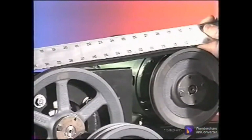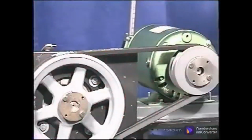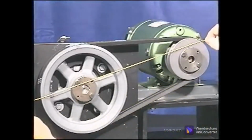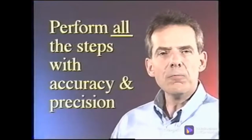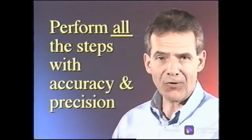When installing new belts, set the tension 1/3 tighter and check it after the first few hours of running, adjusting it if necessary. Use a straight edge as a deflection guide, or in multi-belt drives, use another belt as the deflection guide. When the tension is properly set, make a quick check that the alignment is still true, install the belt guards, and start the machine. Be sure to perform all these steps, being as accurate and precise as possible to ensure a smooth running belt drive.